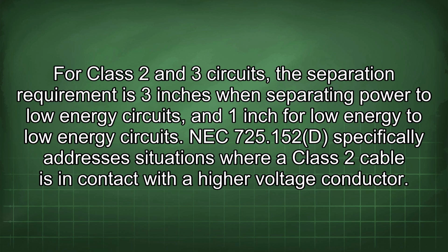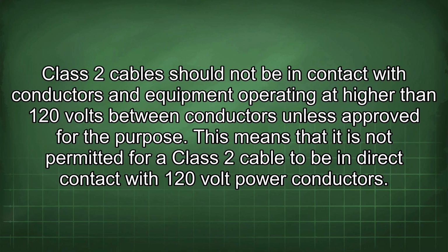NEC 725.152(D) specifically addresses situations where a Class 2 cable is in contact with a higher voltage conductor. Class 2 cable should not be in contact with conductors and equipment operating at higher than 120 volts between conductors unless approved for the purpose.